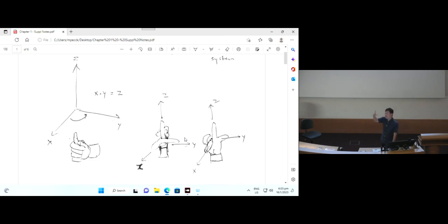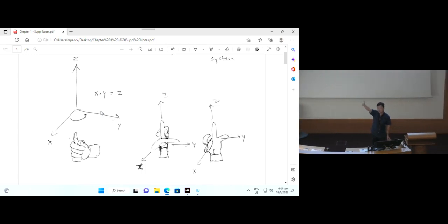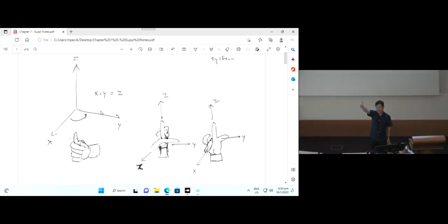When you fix a coordinate system on a frame, on a link, you specify your x and y, and then you'll be able to tell your z. A lot of the time you have to use your right hand. So this is called a right-hand coordinate system. If you turn from x to y, the turn will give you the z direction.